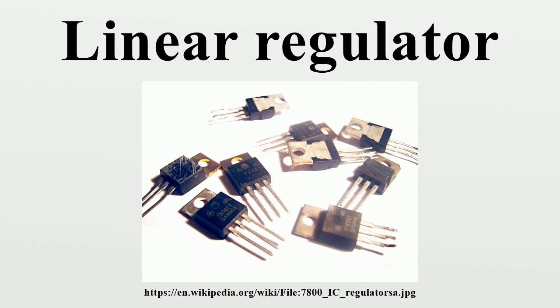Shunt regulators. The shunt regulator works by providing a path from the supply voltage to ground through a variable resistance. The current through the shunt regulator is diverted away from the load and flows uselessly to ground, making this form usually less efficient than the series regulator. It is, however, simpler, sometimes consisting of just a voltage reference diode, and is used in very low-powered circuits where the wasted current is too small to be of concern. This form is very common for voltage reference circuits. A shunt regulator can usually only sink current.